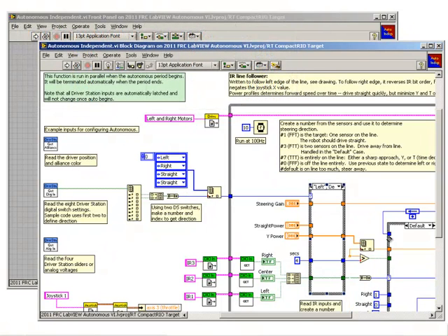Once inside the while loop, we notice that the chosen path is being wired into a case structure, and determines which case will run throughout the loop. For now, we'll assume that the left case was chosen. In the left case, the steering gain control is being passed through, as well as the Y power, a number 4 labeled seconds, and a Boolean array of the 3 infrared sensor readings. For now, these values are just being passed through the case structure and are not being used.